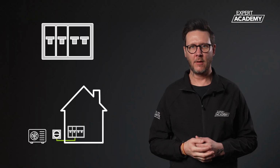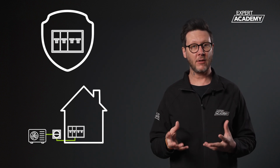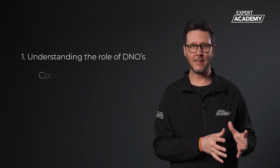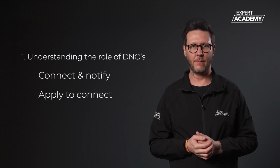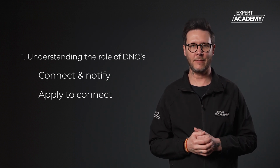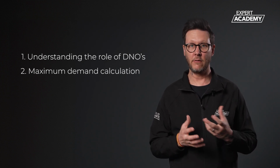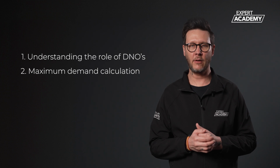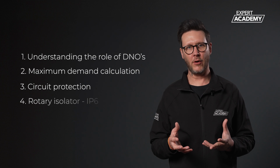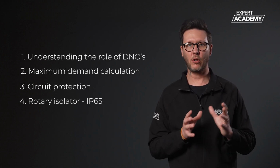Plenty of information here. Feel free to re-watch this video, take notes and digest. We have covered off several key points. Number 1, understanding the role of DNOs and the importance to either connect and notify or apply to connect with them. They need to be aware of renewable installs on their network to guarantee its safe and efficient operation. Number 2, the necessity of conducting a maximum demand calculation, the result of which will determine the path with the local DNO. Number 3, the correct type of circuit protection. And number 4, the need for a rotary isolator rated to IP65, which should be installed locally to the heat pump.